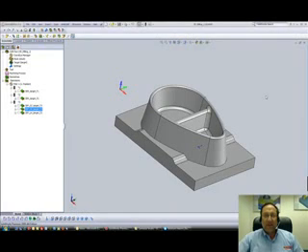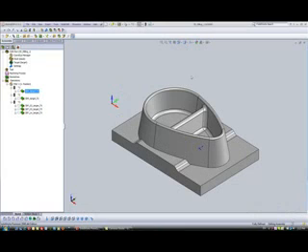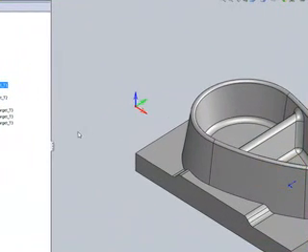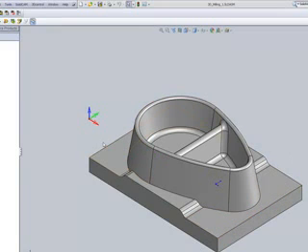I'm Sydney, your SolidCAM Professor, and in this session we'll be showing you the machining of this part using 3D milling. We'll start off by doing a rough cut on this part itself, and then we'll be doing a rest machining rough cut to clear out the areas where the first tool could not enter. We'll continue by doing a constant Z cut on the steep walls and a constant step over on the shallow areas such as these radiuses and this floor inside over here, and we'll finish off the outside by doing a linear cut on that floor.